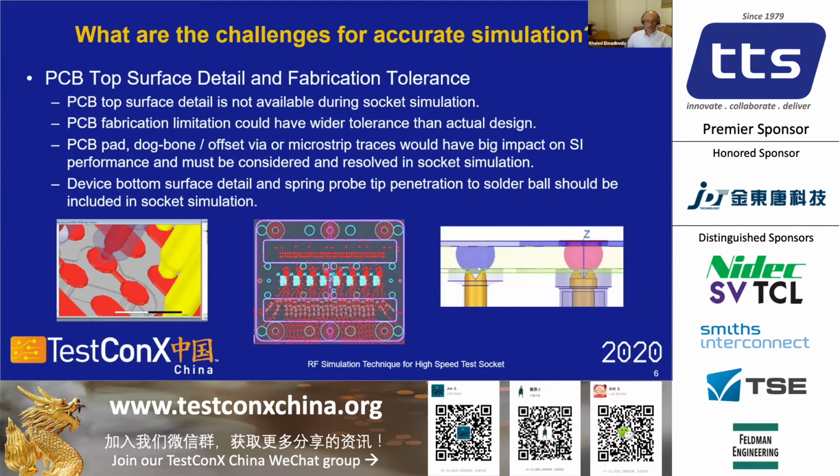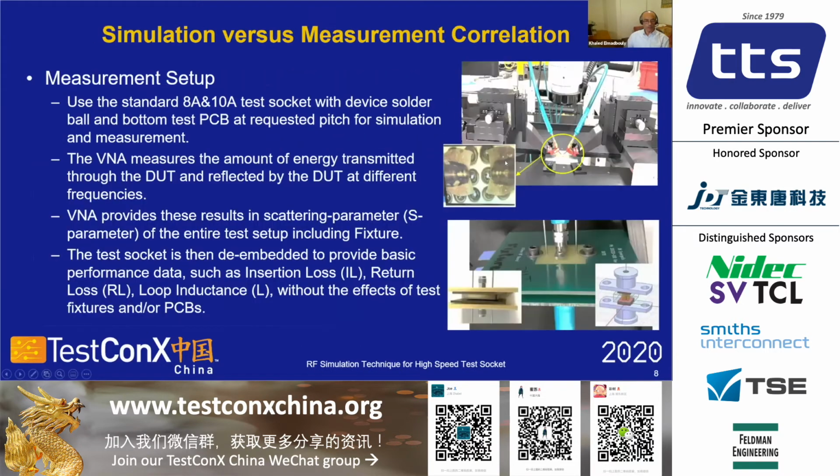And also we need to capture the solder ball penetration by the spring probe in a test condition. This is also critical because you will have different probe height, different probe penetration inside the solder ball. This can also affect the simulation result. Because of all of that, we did an extensive study, in the next slide, to see the impact of a PCB design like that when we interface it with a socket or the probe head.